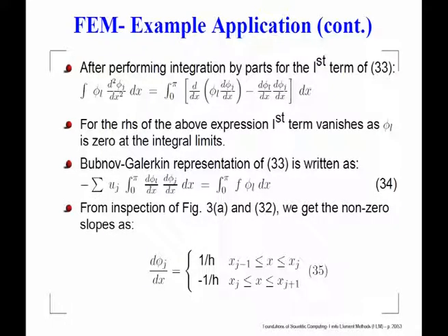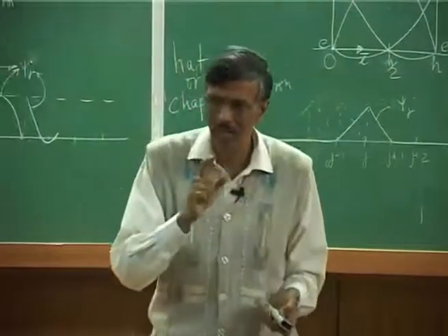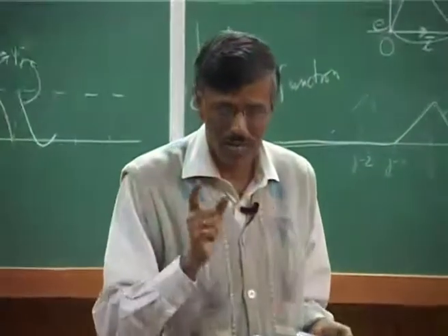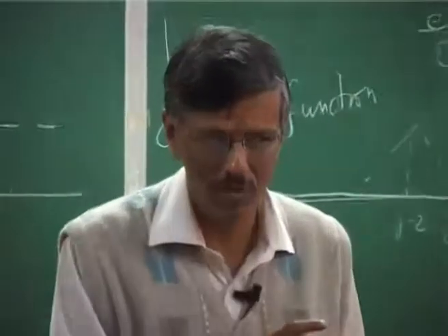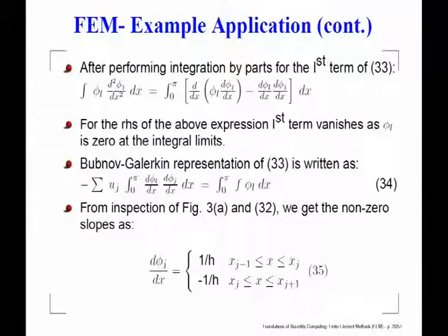At the end of the element, we are not going to satisfy the differential equation at the end, right, at 0 and pi. So, in all the cases, at x equal to 0 or x equal to pi, the first part will give you 0 contribution. Then you have come to this. This is what is called the weak form. See what has happened: we are not satisfying the governing differential equation, we are satisfying an integrated form of it. That is what we did. We multiplied by phi L and then we integrated. That led to dropping of this term, and then we get this.